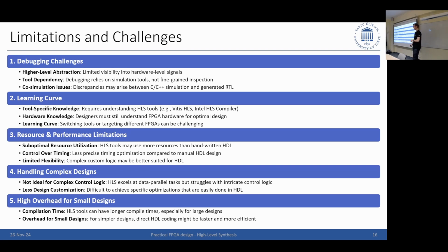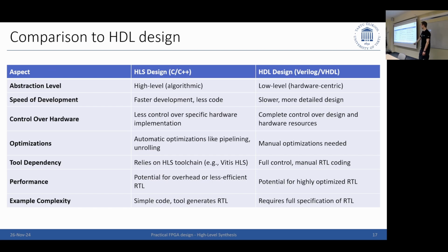But if you need to then integrate also an SDRAM and a camera and whatever into this, then you have a mixed design approach. I might want to write my algorithm in HLS and then do the things around. So, just in a nutshell slide, we have covered all this, I think, in the lecture, but I thought such a table might be useful for anyone who then later wants to go into it.